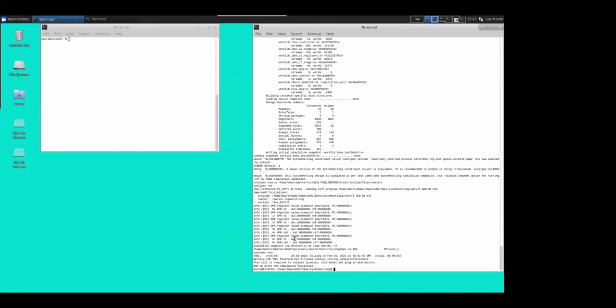Now, the first thing I would mention about this is that unfortunately we don't really have a lot of information here regarding the flow of execution that led up to this point where we saw the difference. And this is now where we start to get into the details of how we extract more information whenever we get problems with the state comparison between the RTL DUT and the Imperas DV environment.